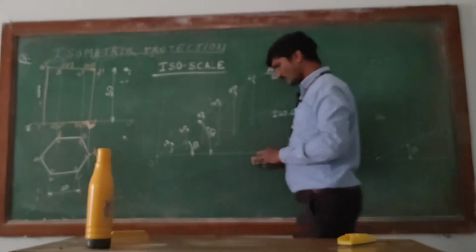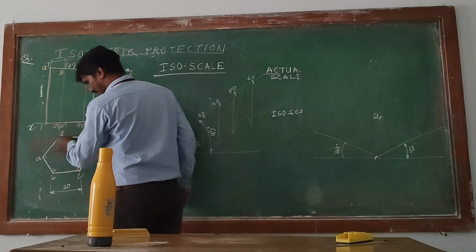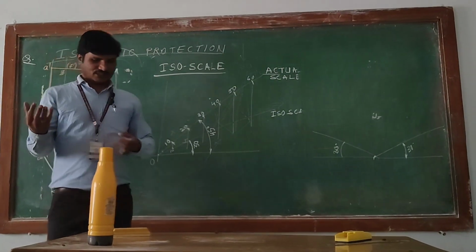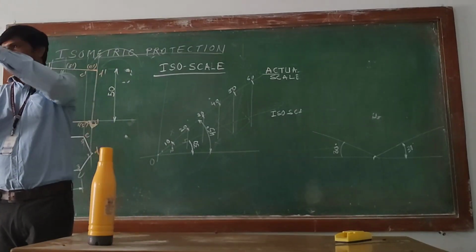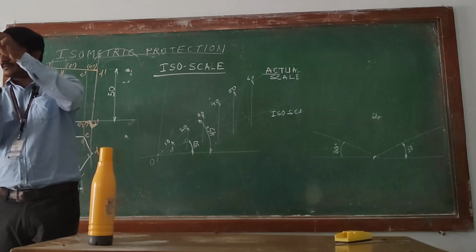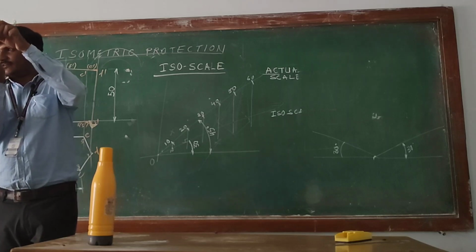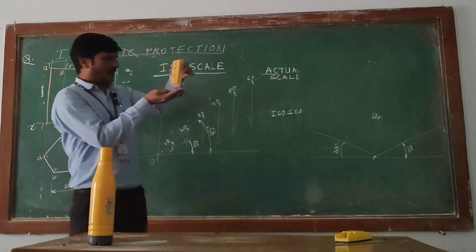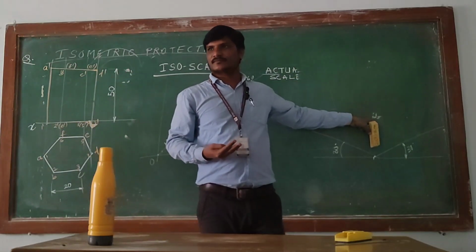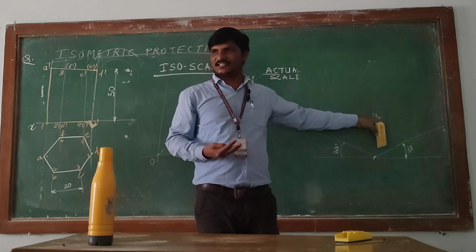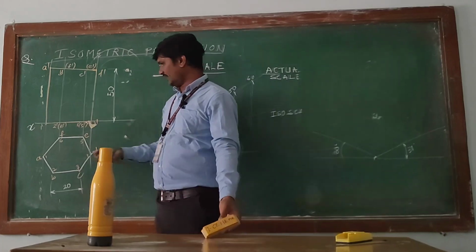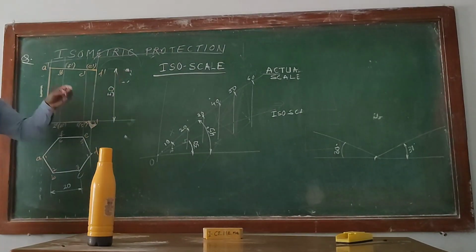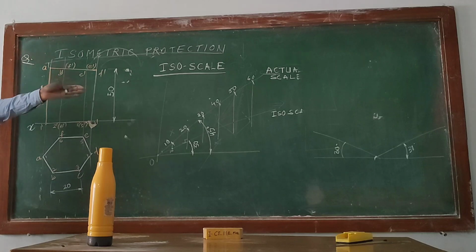After that, I want to transfer this hexagon, because just imagine it is a hexagonal prism, the base having a hexagon, the top having a hexagon. So first I want to transfer the base onto my isometric stand. This is like a stand here. We have to transfer the base first. Here this hexagon I cannot shift directly, because only two bases are there, but here there are different bases.